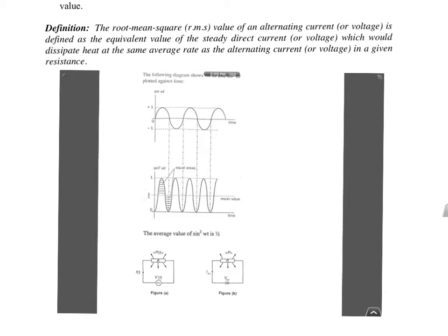Alright, so I just taught you how to convert. You want to convert AC to DC? If you know the RMS, you just substitute the direct voltage with that value, you'll get the same average power. Same thing goes for current. If you want to find out the direct current value to give you the same average power, you find the RMS current of your AC.